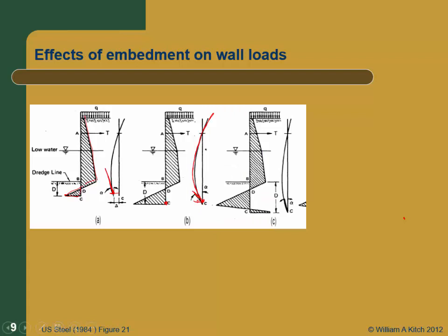And then as I go deeper, what we're essentially doing is decreasing the deflection in the wall down here. So this alpha term here, the angle of this, will actually decrease. And if I get it to the point where that flips back the other direction, I'll actually start to develop some net passive resistance on the backside of the wall as we get with cantilevered walls.